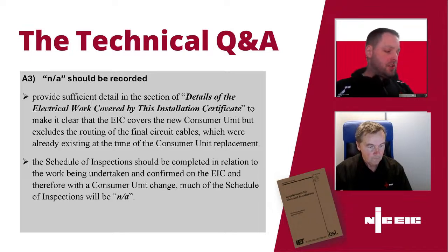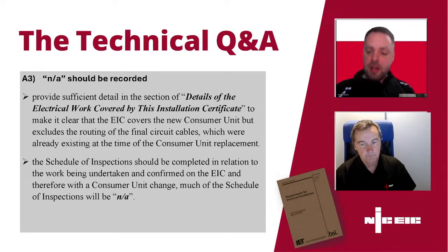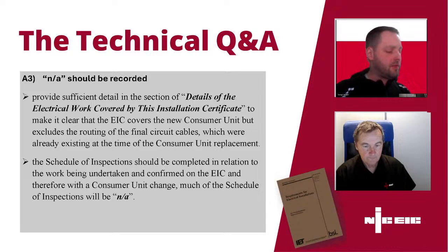No, just that, like what you were saying, that comes up in the field time and time again. So I don't want to change this board, I want to install a separate board because I don't want to take responsibility for this, but obviously it's not. It's so clear to just have that extent of works, details of electrical work clear, and it just reiterates that the certificate is not just for the client, it's also for the contractor's records, and it sort of protects everybody.